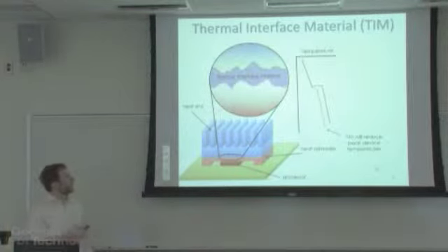So what happens is, if you introduce a thermal interface material in between the 2, you can actually decrease that temperature drop, and you'll reduce the peak temperature of your device, which can increase your electronics longevity and reliability.